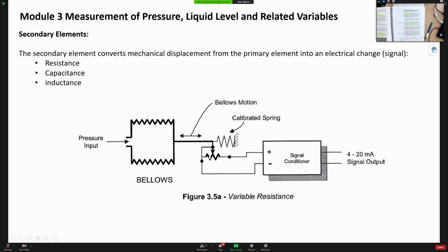This looks like what I think is called a rheostat, and then you have a calibrated spring down here. You probably have a power source inside. You can measure the resistance in here because this is a jumper on this side. So when you measure the resistance, you only measure from this point to wherever this wiper is.